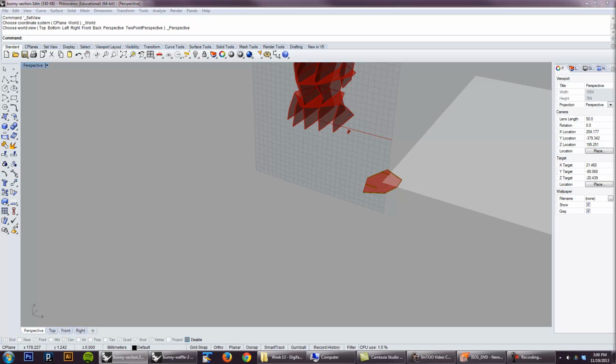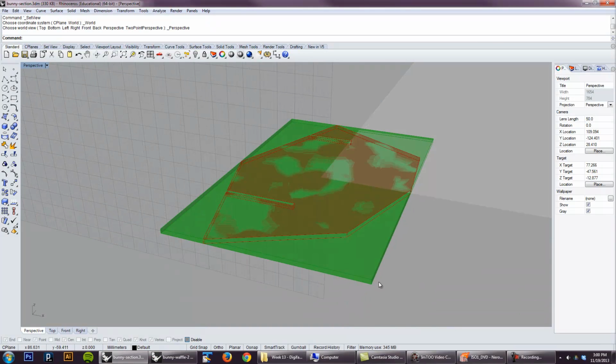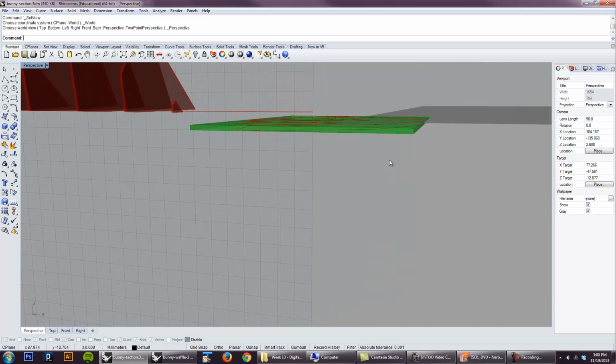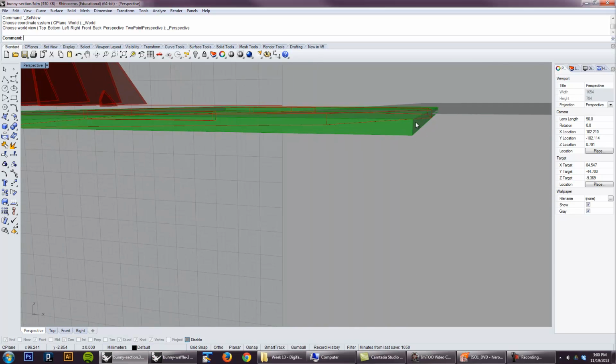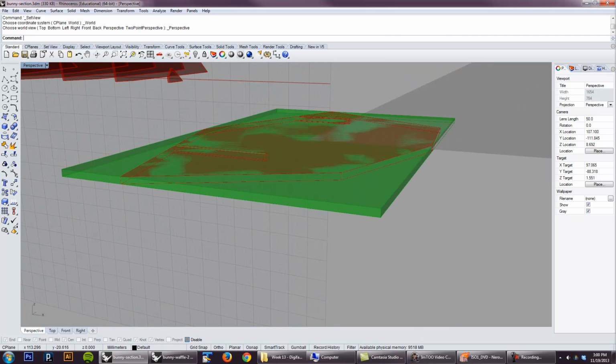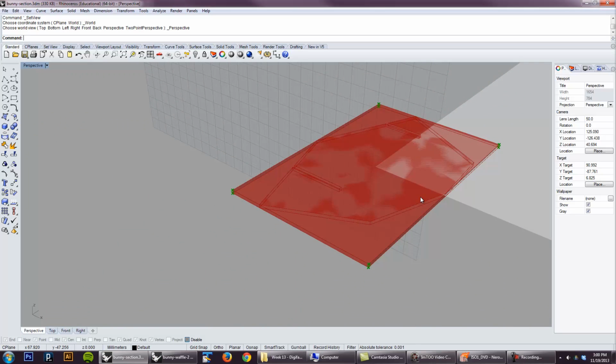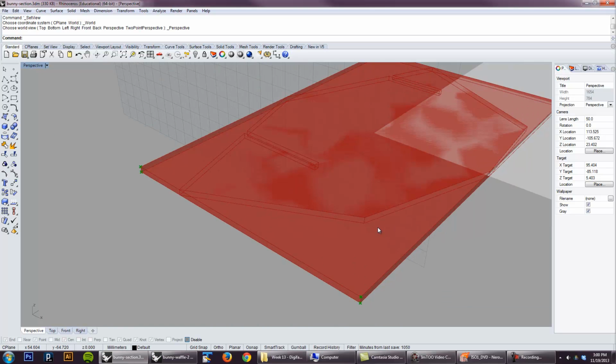So the first step that I'm going to do is just start with a bounding box on this object, and the bounding box is nice because it's going to give us two things. One, it gives us a plane that's perfectly sized to the object, and two, it's going to allow us to look at the height of the box. If we take half of that height, then we can position that plane exactly halfway, so it'll make a perfect intersection. Okay, so I'm going to take a bounding box, and we use the box corners. You can see my 8 corners as we've done before. Just like what we did when we first made sections on the objects.